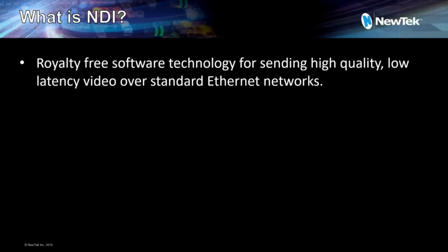It's high quality and it's low latency. So we're talking about video that looks and performs like SDI video. It is compressed, and we'll talk about compression in just a little bit, but it's high quality compression. Nobody's going to look at this video and ask, what did you do to it? It's going to look like video they're used to looking at. Low latency, for most cases, means 1 frame of video or less for transmission time. So you could run this alongside SDI and people are not going to see the difference.